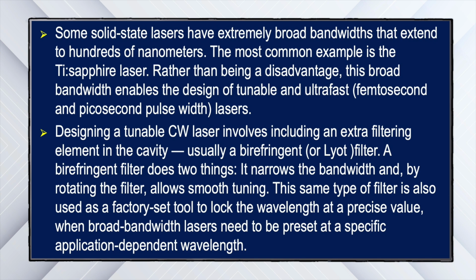The resonator mirror under ordinary condition will not remain the same, because there will be vibration, there will be some heat, so they will just move back and forth. So you must have a certain type of servo mechanism to make the correction and then make it very rigid.